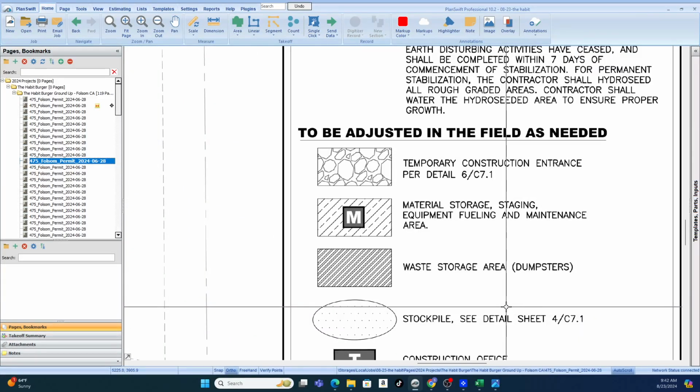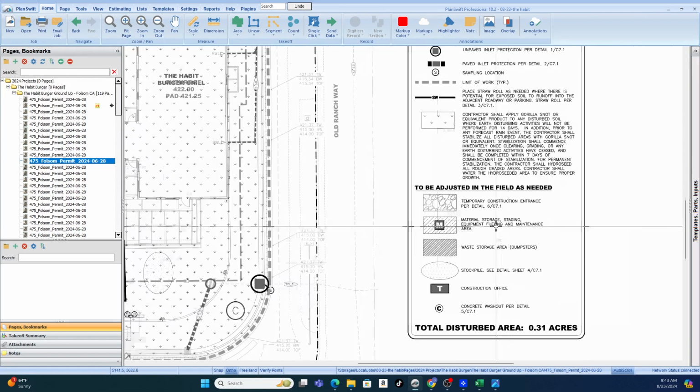For instance, if the cost book gives you up to 4 feet by 4 feet column pads and they don't go any farther than that, well, if you have a 7 foot by 7 foot, how many times a 4 foot by 4 foot is that? So you do the math, right? You say 7 divided by 4, it's 1 point something. And so your 7 by 7 would be 1 point something times in reinforcement, in formwork, in concrete. That's how that works.